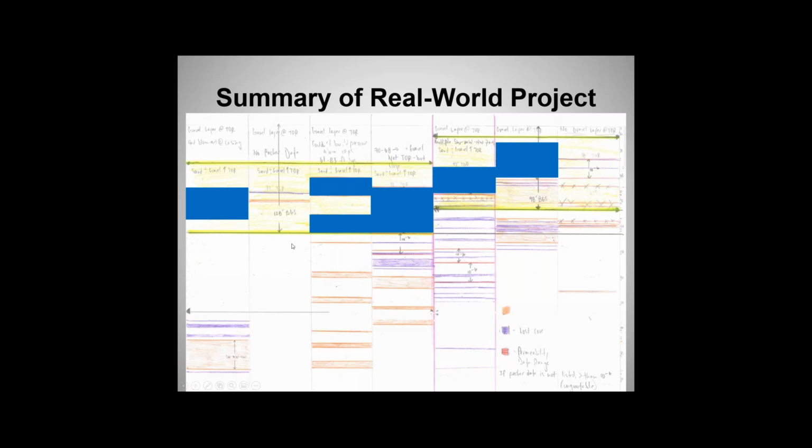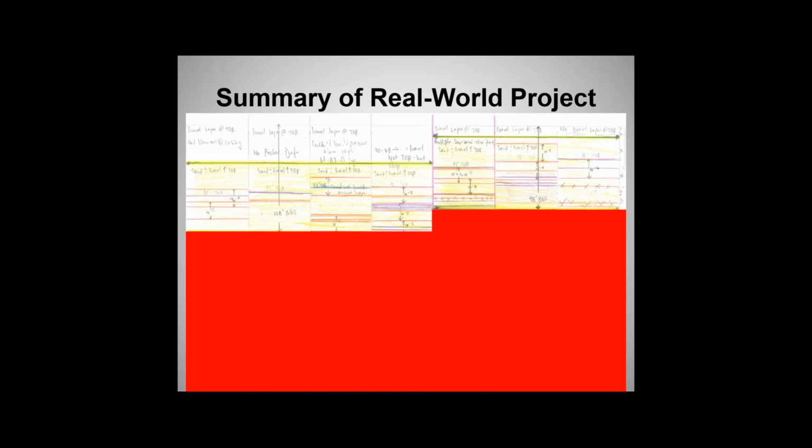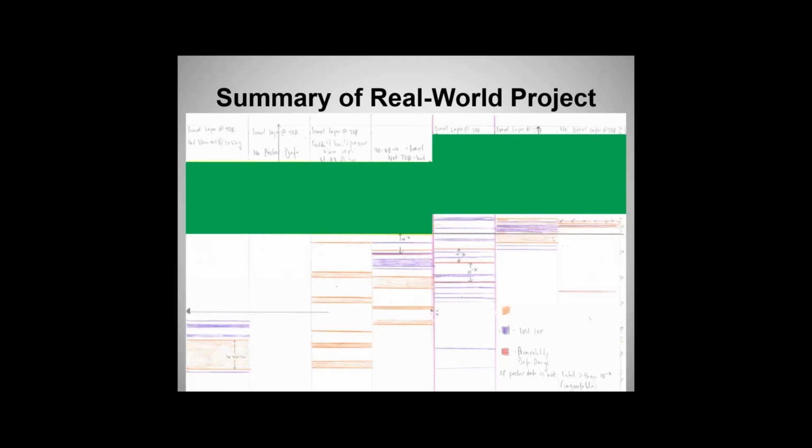This is where you're building the picture. Even though the core looks like this, or you've got a sandy material, or maybe you've got clean fractures at depth in a crystalline environment, and you don't have clay-lined fractures. If you're not injecting water into it, you're not going to get grout into it. So what this tells me is that in this particular area, I'm not going to really inject any grout. But in this area up here, I can do some grout.